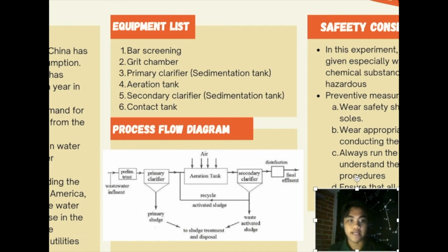Here, the remaining organic sediment is allowed to settle out from the treated water flow. The small solids called activated sludge are allowed to sink to the bottom of the tank, and some part of the activated sludge is returned to the aeration tank to raise the bacterial concentration and enhance the breakdown of the organic material. The waste activated sludge is channeled out to the secondary wastewater tank.